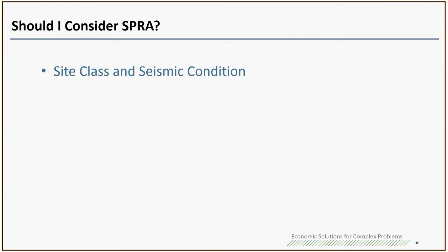Now the question is, should I consider the site-specific response analysis or the ground motion hazard analysis? Well, first, it depends on your site class. If you are site class ABC, you don't need to do that. Also, if your project is located in a low seismic area, you may not need to consider that.